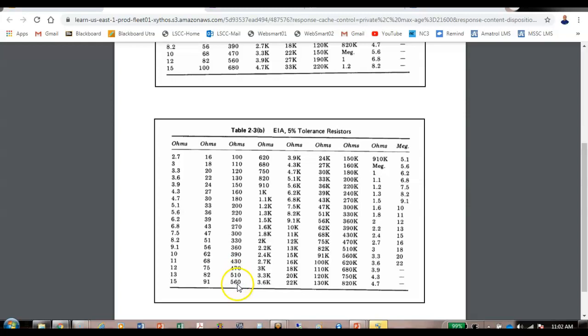You say always go up, so that'll be 560. Well, no, we could go up or we could go down. 15 milliamps is not the maximum. Normally the maximum current flow would be quite a bit more than that. But we can round up or round down. It doesn't make any difference. So 533 would actually round down, right?